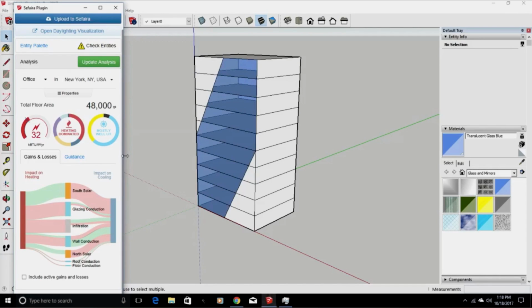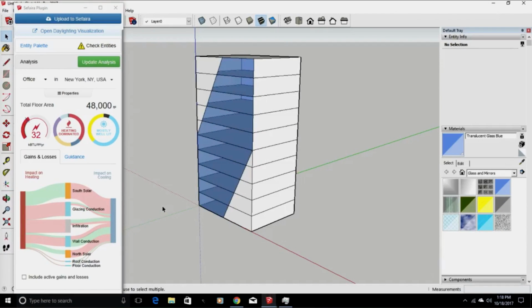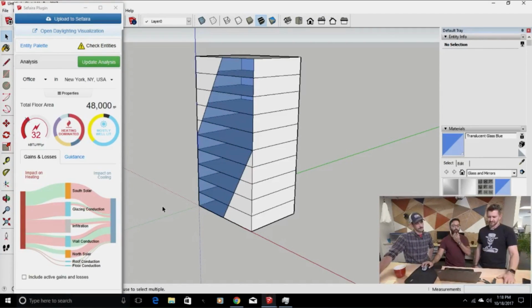Yep. And once you remove all the stuff that's generating heat inside, if this was a building that had nothing in it, heating load is greater than cooling load, still quite a bit because we have so much glass. We're closer to the green line though. So, just for fun, obviously getting rid of the glass wouldn't be as fun. What are some other things we could do to this model to account for all that glass? Can we add anything else or manipulate the model somehow?